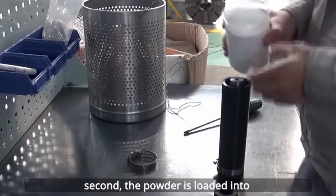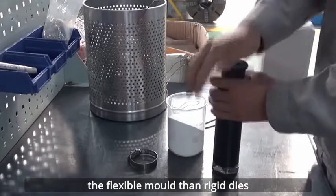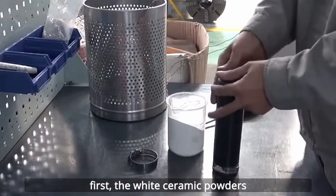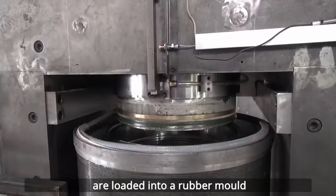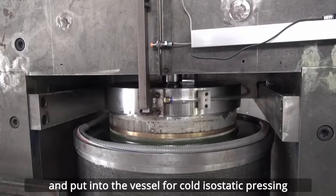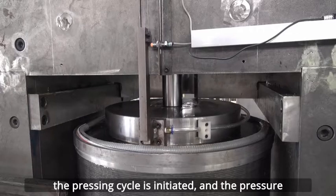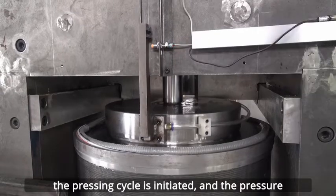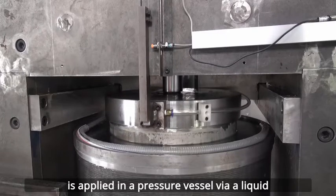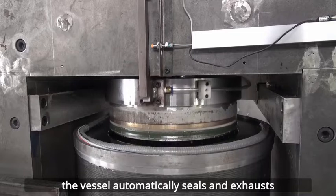Second, the powder is loaded into a flexible mold, not a rigid die. We are watching an example. First, the white ceramic powders are loaded into a rubber mold. The mold is sealed well and put into the vessel for cold isostatic pressing. The pressing cycle is initiated, and the pressure is applied in a pressure vessel by a liquid. The vessel automatically seals and exhausts.